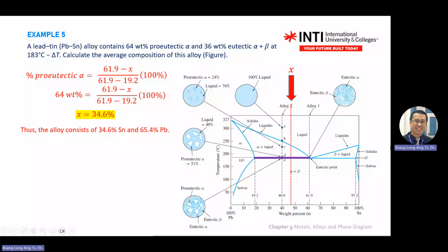Okay, so eutectic is a point where you have a liquid change into two different solids, alpha and beta. Then you have a eutectic point. And also there will be a pro-eutectic point over here where your liquid changes to the first alpha, pro-eutectic alpha here. And if the line falls on here, then you have a pro-eutectic beta here. Right? Okay.